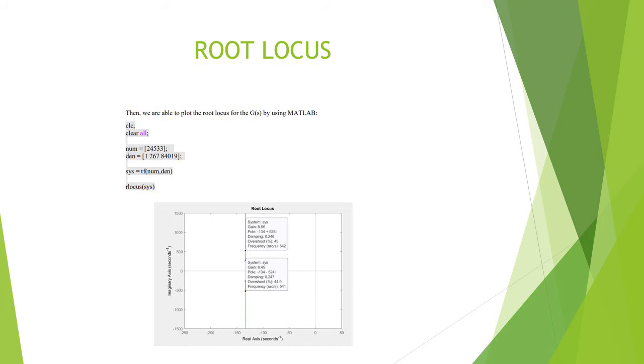We plot the root locus using the program MATLAB. First, we key in the open-loop transfer function G(s) into MATLAB, then plot the root locus.